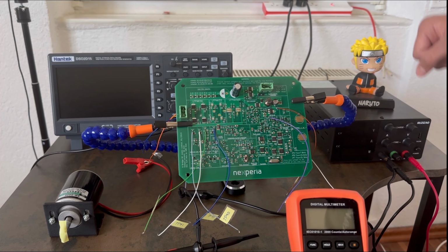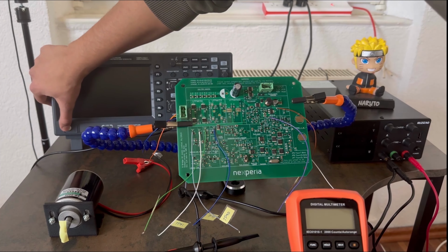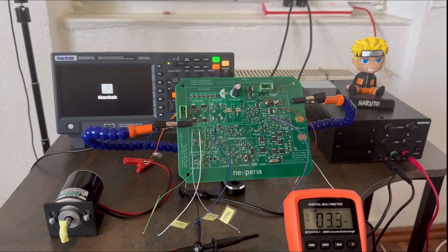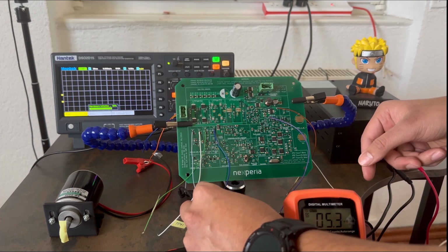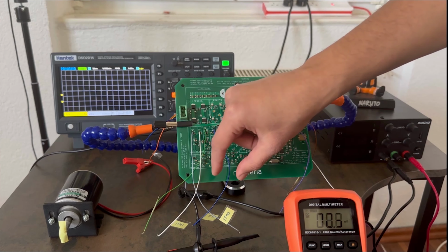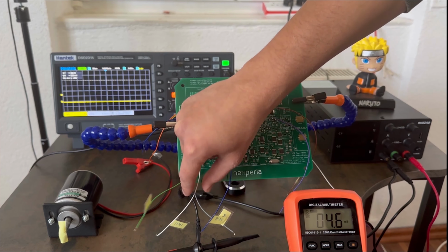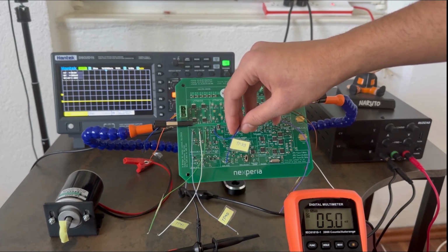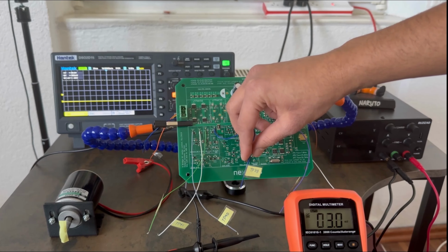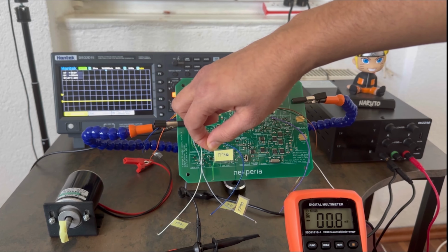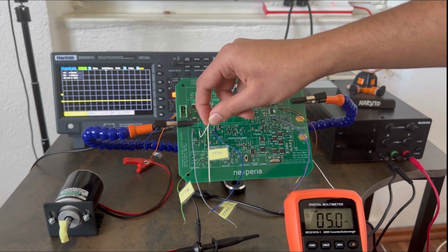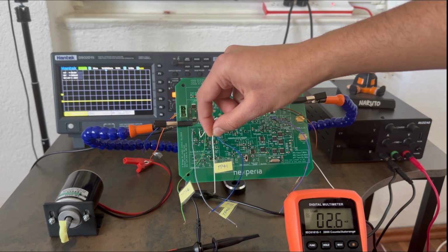Now we'll check the MOSFET gate signals and verify whether the working of the circuit is as expected. I turn on the scope, multimeter is on, all things are connected properly. I have all the test points out here. We need to check all the gate signals of these MOSFETs Q1, Q2, Q3 and Q4. Test point 39 is nothing but the MOSFET Q1's gate. TP36 is connected to Q2's gate. TP40 goes to Q3 and TP41 is connected to MOSFET Q4.